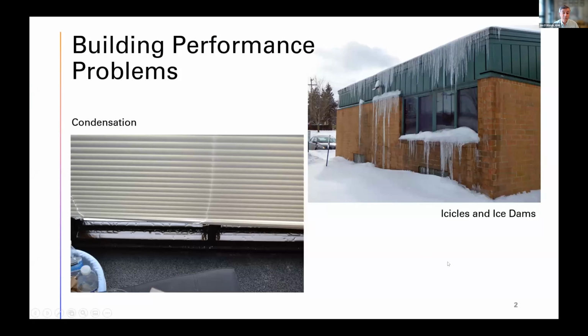It's all about building performance, right? And what does that mean? We want low energy buildings. We want buildings that don't cause problems and don't cause discomfort. These are real world examples from things that I've seen. And what's funny is a lot of times they're caused by structural elements in the building envelope. You get condensation in the windows. It might not be the window. It might be the thermally unbroken lintel above the window opening.